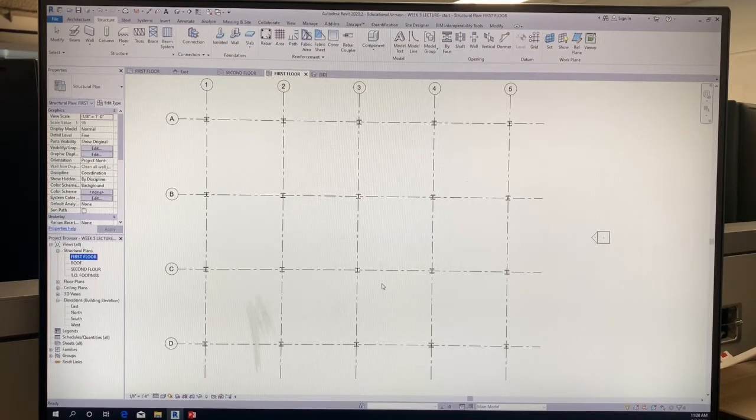Normally, if I wanted to create that wall going upwards, I'd be on the top of footings level and create it there. But what we're going to do is create it from the first floor, but start it at the top of footings level. So let's go ahead. To create this, it's just a wall. So let's click onto the wall command.